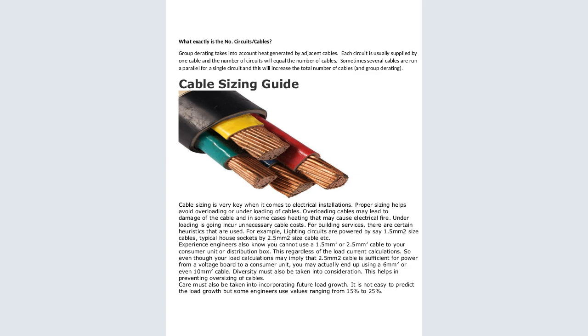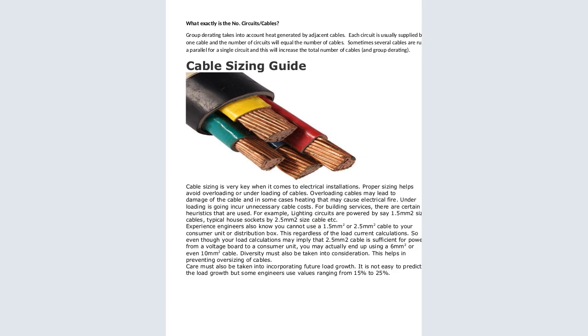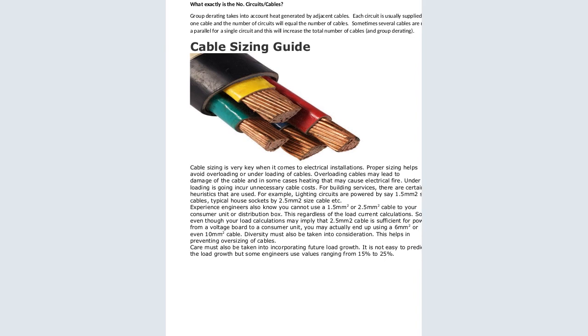It's because of the amount of load that is expected to be consumed through the distribution board. For example, a distribution board distributes power to different floors. Mostly distribution boards are used in storey houses. You cannot get a distribution board in a single unit, meaning a single household. A single household normally uses a consumer unit. But a storey house has different floors, and each floor is a combination of several units put together.